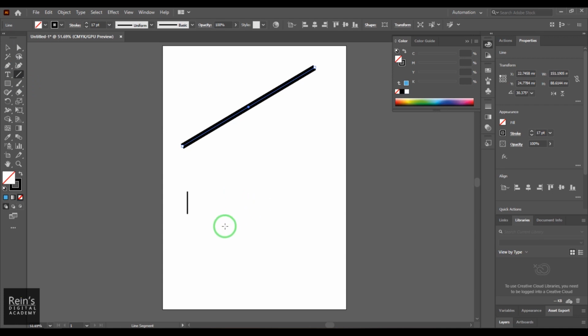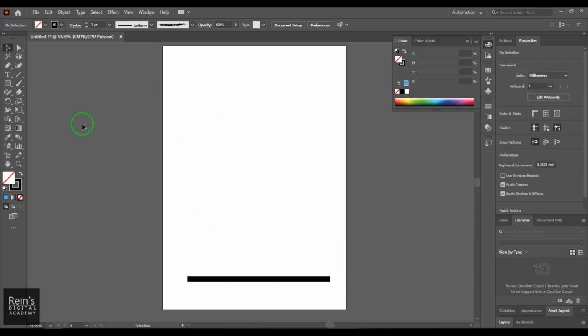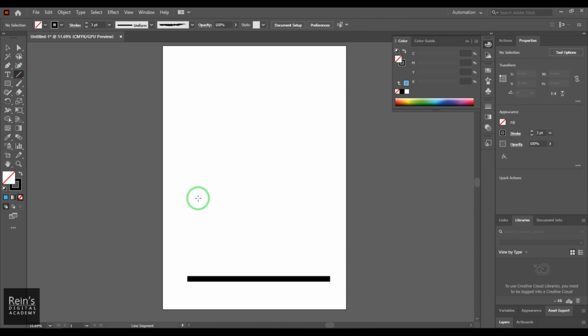Apart from that, when you are drawing a line, if you hold Shift, then you can create this line at 0 degrees, 45 degrees and 90 degrees alignment. I'm selecting these points and just deleting them. While I'm creating these line segments, wherever I've clicked and dragged, if I'm holding Alt, you're getting a line segment from that center going out.